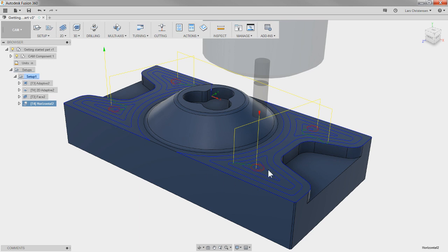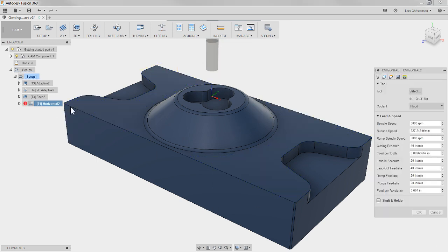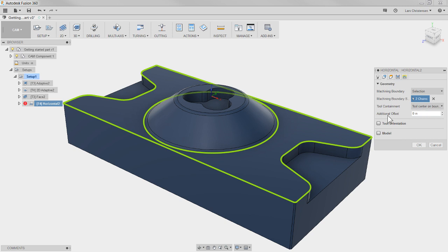But you will see that it broke up the toolpath, and it enters on the center, on the stock itself. It comes right down. And if you have done any machining, you're thinking, well, can you just start from the outside so you don't plunge down in material and just come in from the side? That's where, if I go in and edit it again, you could use that additional offset.